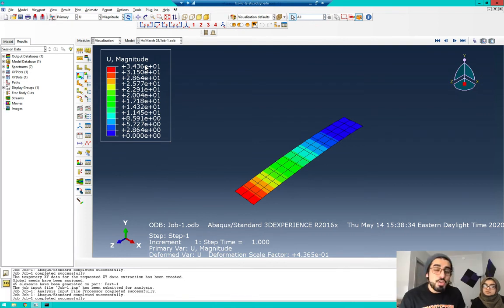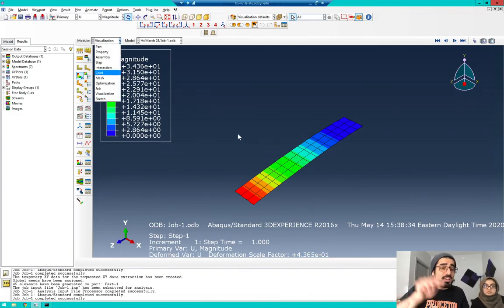Remember what I said? We said the bigger the mesh, which means look how big the mesh is here, big sizes, it means we're stiffening the system, we make it more stiff, right? So that's why it's harder to bend that ruler. The ruler that is constructed in Abaqus is created in a stiffer way. Now, if I do it again and use a bigger mesh size, it's going to be more stiff.